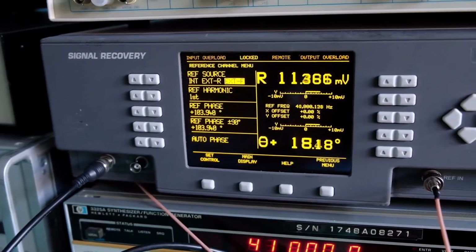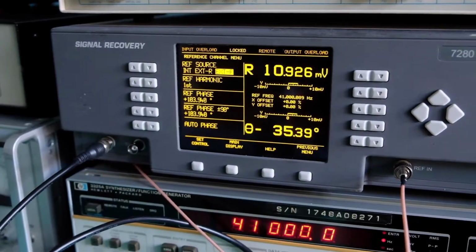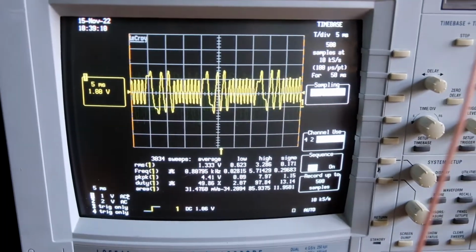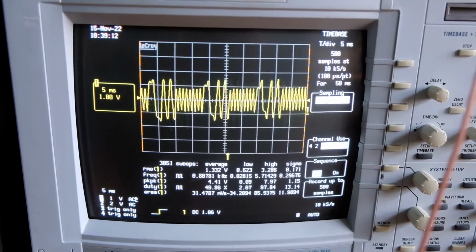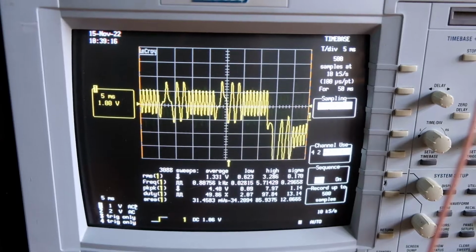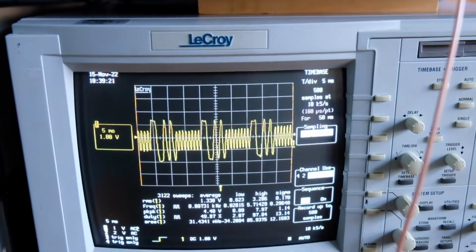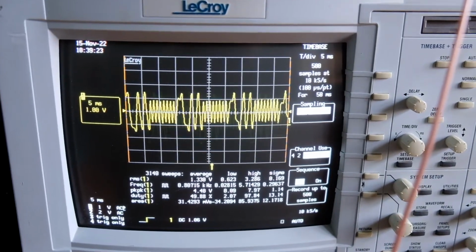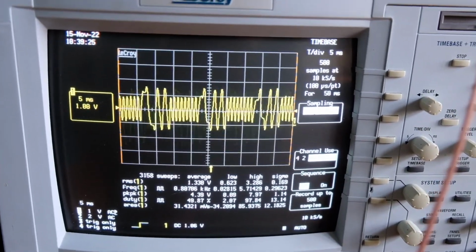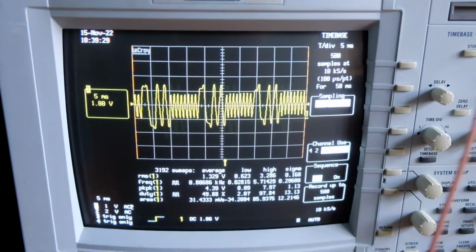And you can see the signal is fairly strong, usable data coming out of this lock-in, and as you can see over here, this is the recovered data coming out of the lock-in X magnitude output, and it's fully usable in terms of it basically compares well with what is going in to this ultrasonic sensor. And if this is decoded, it should produce the same data that is being transmitted up there.